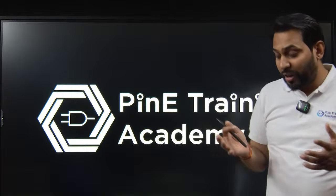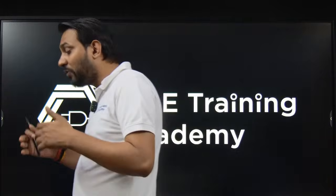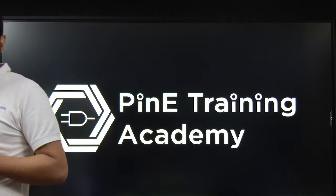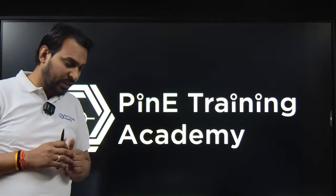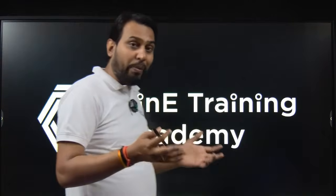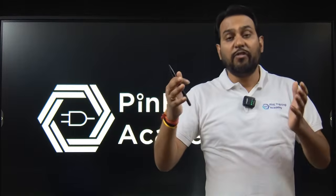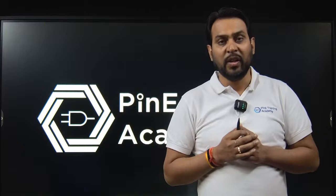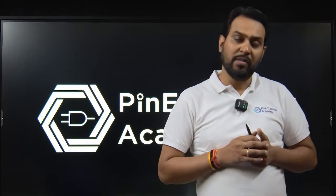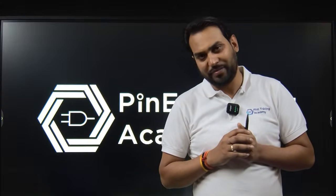Last point, we cannot say that the MOSFET acts like an inductor. We can design an inductor with the help of MOSFET circuits. So you can use an op-amp. With the help of the op-amp, you can design it in this way so that V and I have the relation V is equal to X di by dt. So X becomes an inductor, because the op-amp is just a mathematical tool in analog circuits.